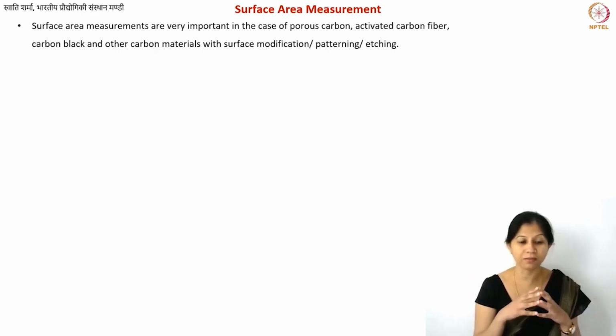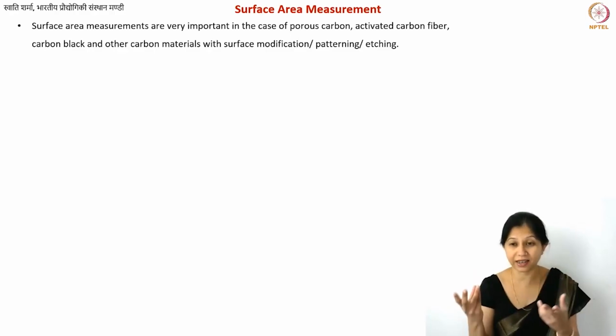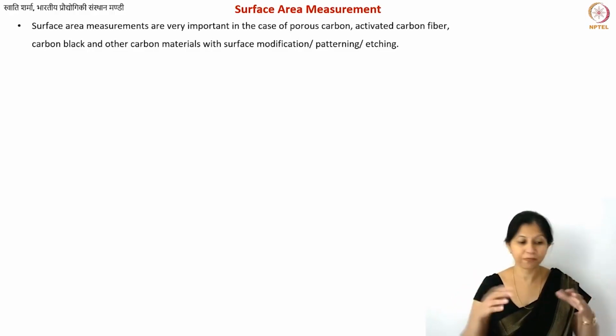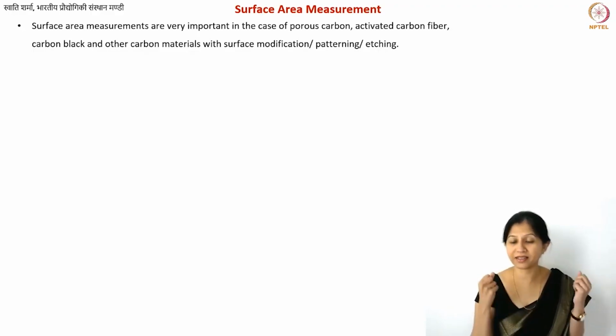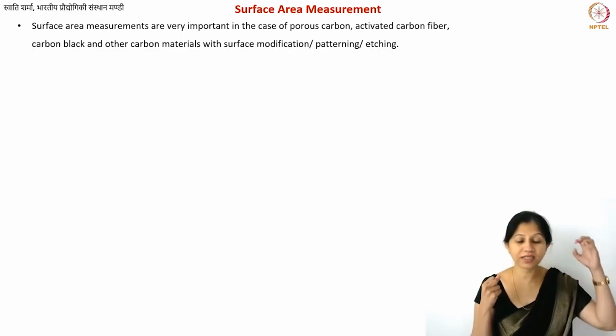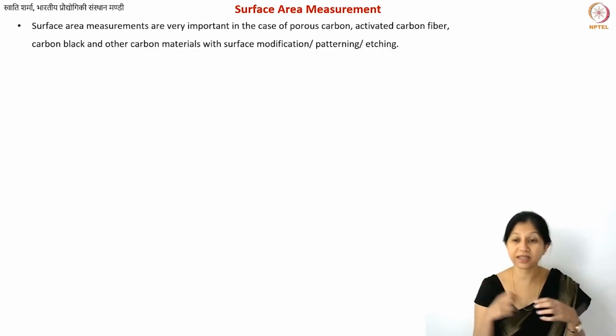They are not, however, the same. It's not that every time you induce porosity, you will have a surface area increase, because as the name itself suggests, it's just the area. It's a 2D thing. So if you're inducing some sort of volume porosity, it will increase the surface area if and only if your pores are reachable from the surface. If it is closed porosity, you already have an impression of it, and maybe I'll describe a little bit more. If your pores are closed, it will not really reflect in your surface area measurements.